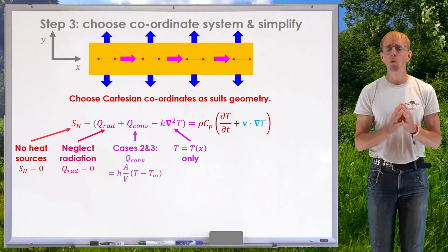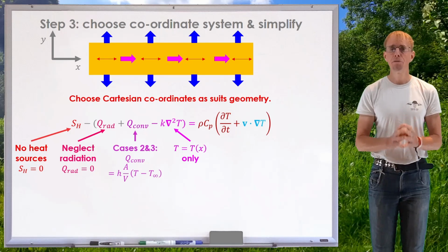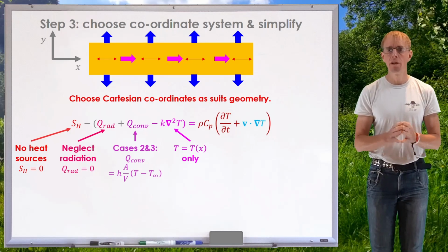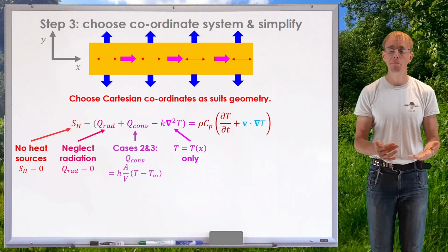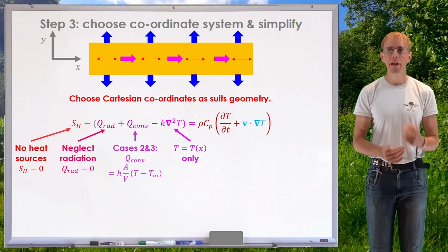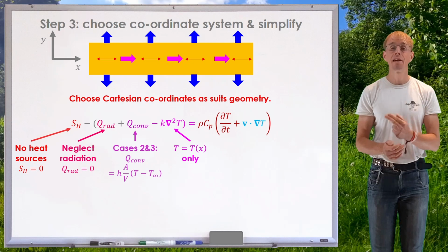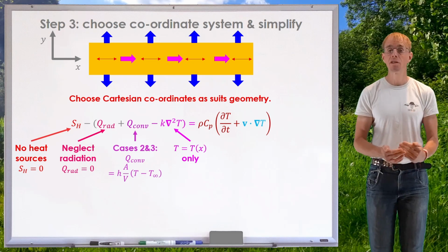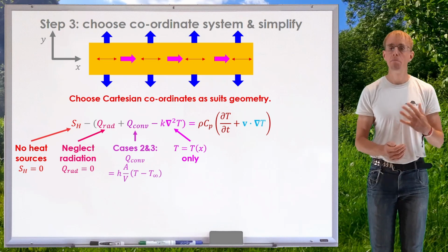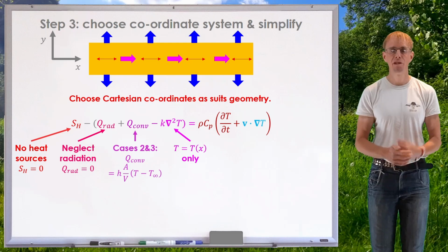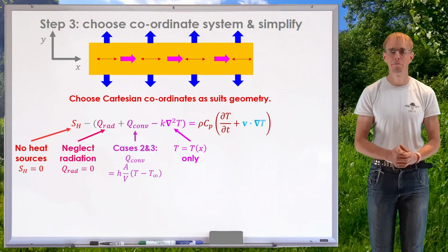Okay, let's look at conduction heat transfer. I have already justified this problem as being a one-dimensional heat transfer problem because it's got a low Biot number, less than 1. That means my temperature gradient is only going to exist along the length direction. So T is a function of x only because of that low Biot number. This is a nice simplification.